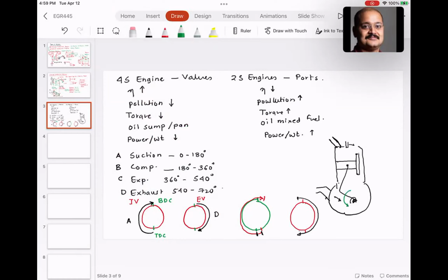this intake charge is compressed, and then it actually goes from this transfer case onto the front and gets continuously compressed. When this piston goes to the top dead center, you get a spark. So there is a spark plug, you get a spark, and basically this spark plug propagates the flame front, and you have the expansion stroke.